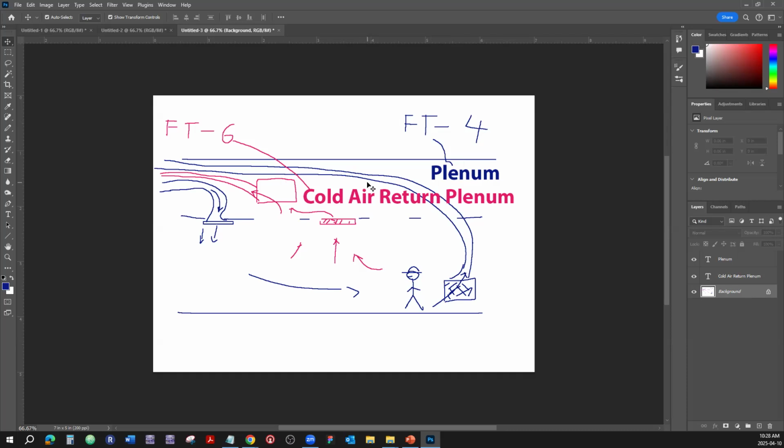If you have cold air return plenum, and if it's an enclosed raceway, such as EMT, electrical metallic tubing, which is basically metal conduit, it's an enclosed system, then you can use FT4. But you cannot use FT4 in a free air run, so-called free air, which is not enclosed, in a cold air return plenum. And the inspectors are really, really specific with that. When the inspector comes to receive the building, before giving it to public use, they are going to notice that in half a second if you pull the wrong type of wire.